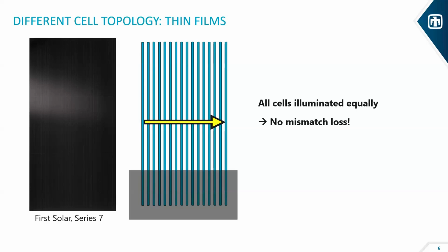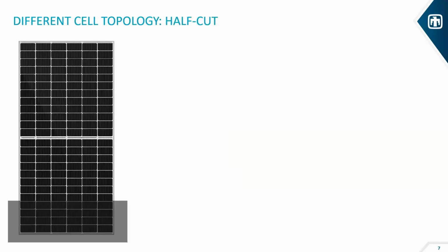So for thin films, that's actually not necessarily a reason to do backtracking, because you're not going to get more power out of it. We would take that extra incidence angle loss because we're tilting it backwards and have the irradiance the same, uniformly, but we wouldn't have a gain from it. So for most thin film cells, we're not actually doing any kind of backtracking. That comes down to the module technology.